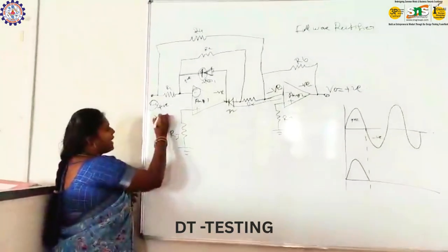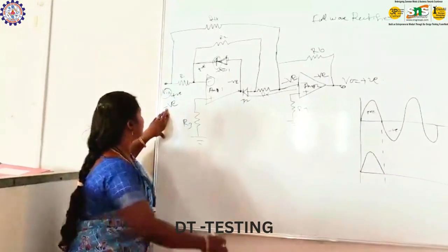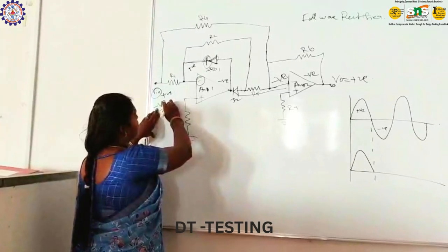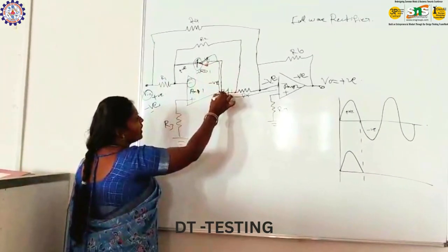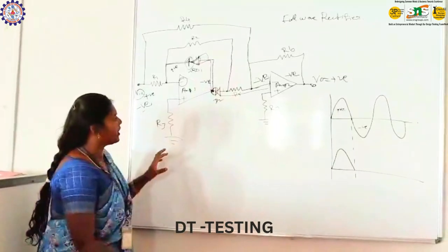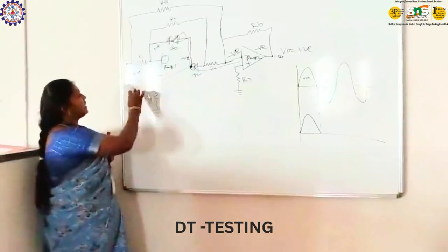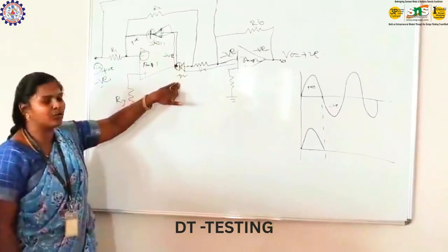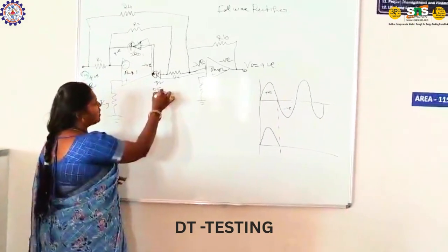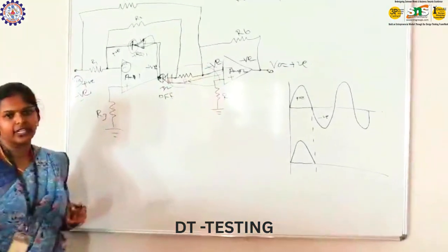Second, I will apply negative voltage to the amplifier 1. So here I applied amplifier negative signal. The D1 will be enabled. That signal goes to the D2 diode. So the negative signal is applied to the circuit and D1 will be enabled, but D2 goes to off condition. So there is no connectivity through this R5.